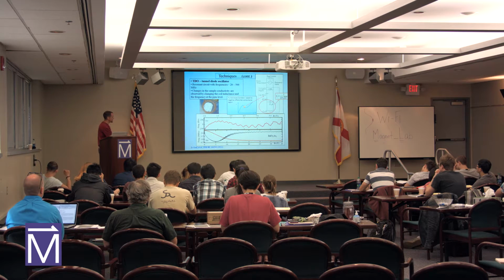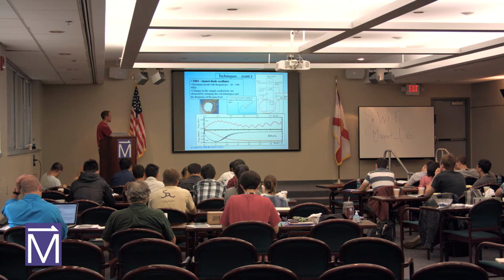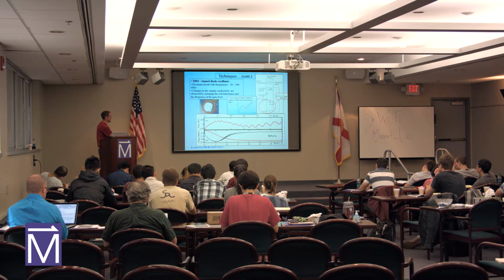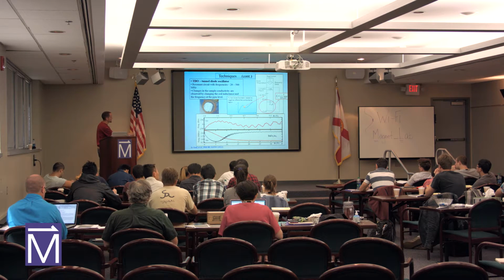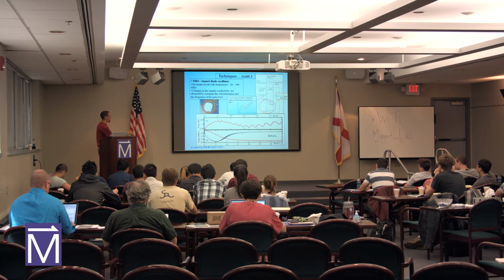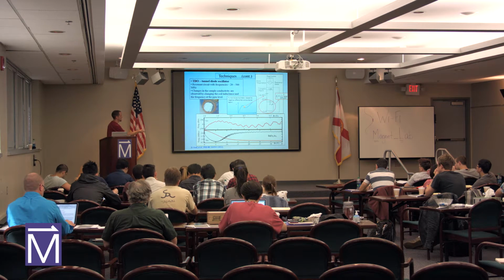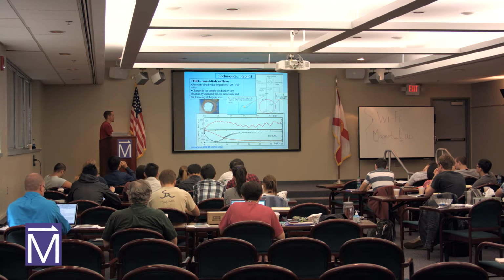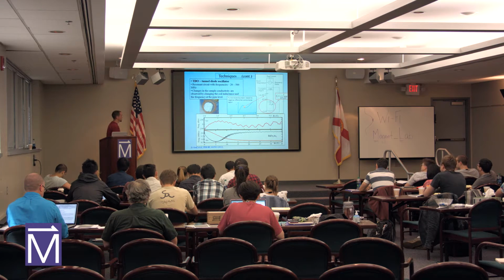Okay, there's nothing interesting to see in this red trace, but if we take the derivative of this trace, we can see tiny changes you can't see here in this black trace. So there's actually lots of oscillations in this raw data. If we focus on just the low field end of the data and we subtract a background away, between 3 and 6 Tesla, we see oscillations this small. The amplitude of these oscillations is as small as 50 hertz for the frequency change. With our resonant frequency of the circuit being 50 megahertz, that gives us 1 part per million resolution using this measurement. So it's incredibly sensitive and a useful technique that you can use that's contact-free.